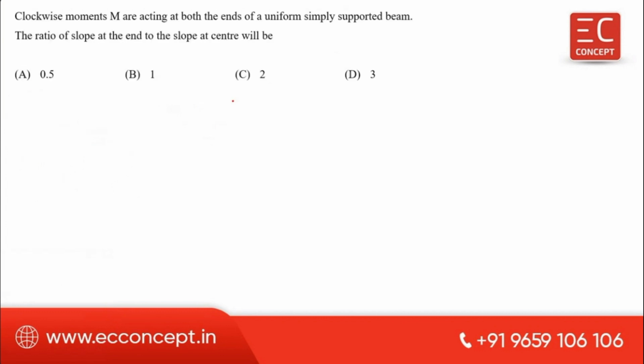Next one is, I said, for a propped cantilever beam subjected to moment M, this M is required to produce a rotation theta, then here M is equal to 4EI by L into theta. Here half will be transferred.